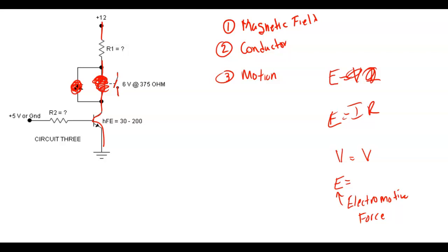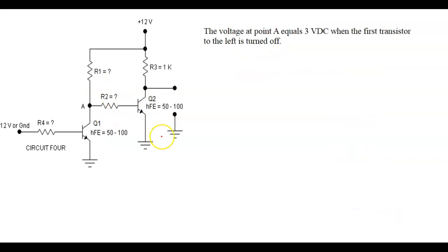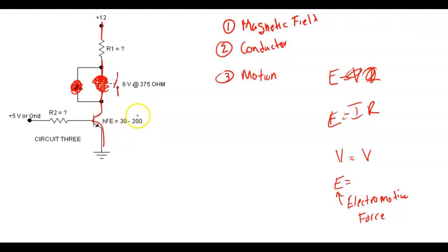So what would happen if I didn't have that little diode? We have a breakover voltage right here. The breakover voltage for a 2N3904 is only 60 volts. So if I didn't have that diode in there, as soon as I turned that off, I'd pop my transistor just like that. So anytime you see this in a DC circuit, especially PLCs, most of your PLCs put out 24 volts, and if you want your PLC to bring in a relay, you better put a diode across that port, or you're going to be replacing an output module sometime in the future.